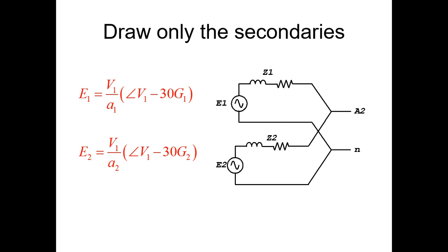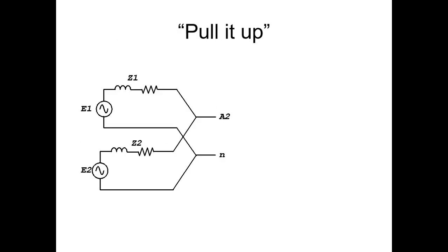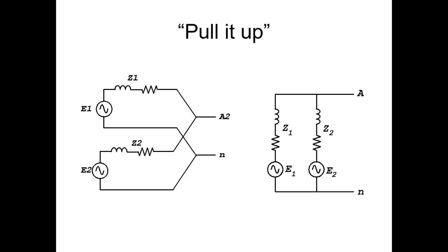Let's trim the secondary. Let's stretch it like so. Long. It is the same circuit, right? There we see that if there is no load and E1 is not equal to E2, there's going to be a circulatory current with parasitic losses that we do not care for. Do not confuse the term parasitic in this context with the one we used in the core. No, this is not about eddy currents. It is about a current that circulates in that connection loop.